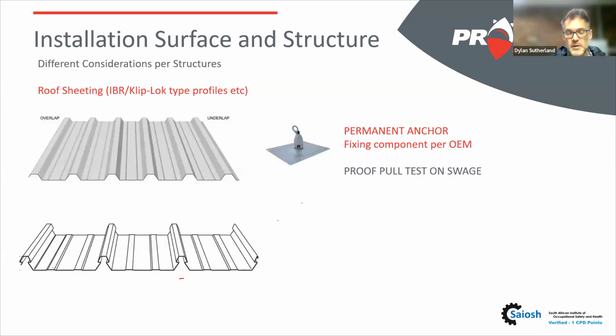If that person experiences a fall and they are 9 meters away from that anchor point, they are going to fall 9 meters toward the ground. They're going to generate force during that 9-meter fall, and quite probably they're going to rip the whole system off the sheet. So what I'm trying to say is the cable's the cheapest component.